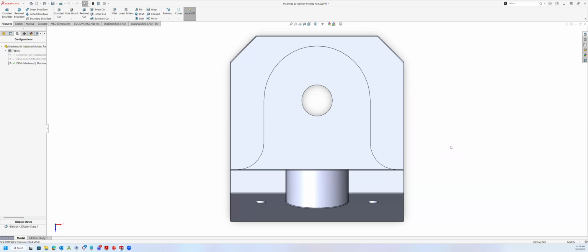Yeah, and that goes to one of the key considerations: don't over tolerance if you don't need to. There are going to be some products that do require very tight tolerancing. However, if not needed, try to stick with standard tolerancing, as it will help dramatically in saving on overall costs. Can you talk about what you would define as standard tolerancing?